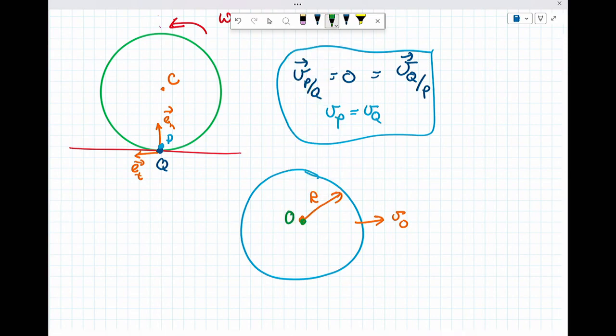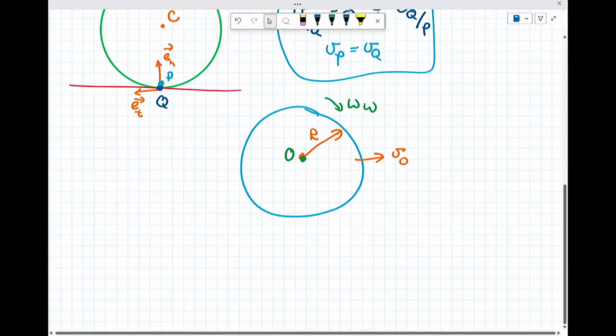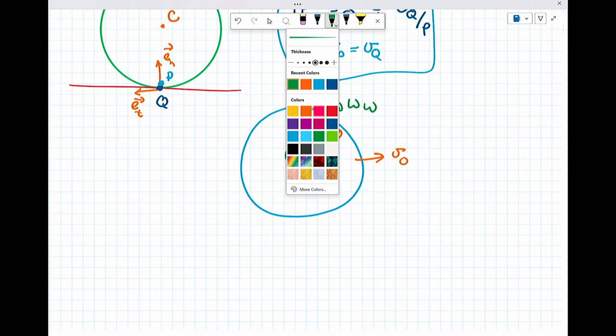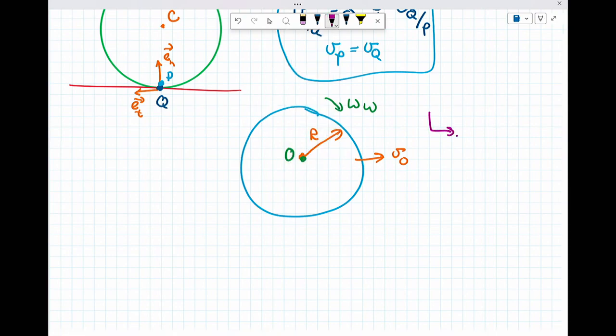And so if I have, say, a wheel that's rotating around and it's moving forward, V naught and omega look like that. And again, and really important, if you do anything with vectors, make sure that you just put your positives down. So x is positive to the right, y is positive up, and counterclockwise is positive. Omega of the wheel.